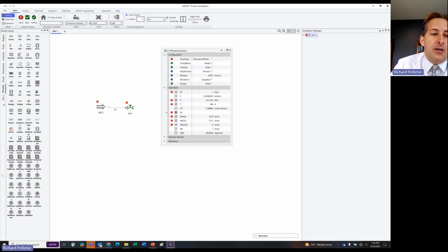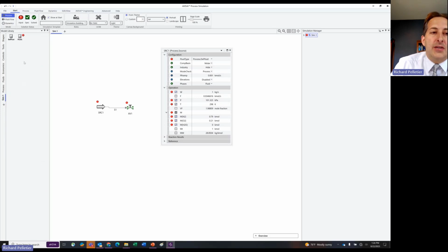So a good example of a custom equipment model might be you take this drum and you add some kind of additional equation that the drum isn't already calculating, some additional property you need to calculate for, right? So you could copy this, you can paste it into here, you can edit this one and then use this on the canvas, right?